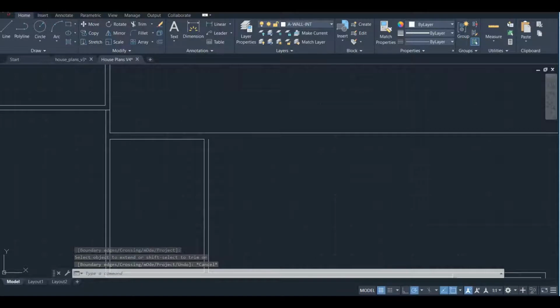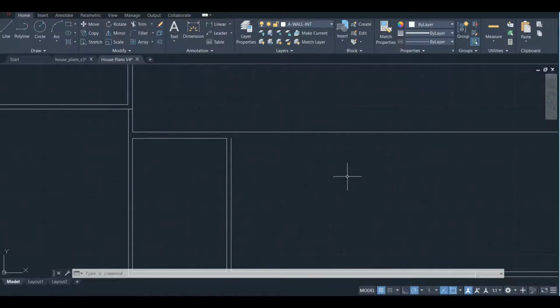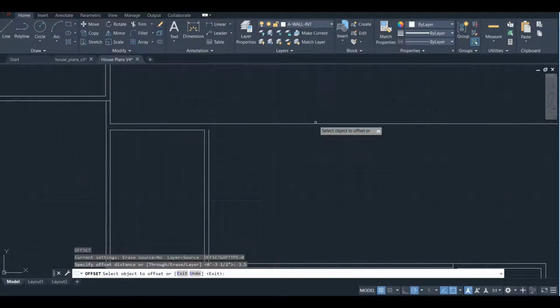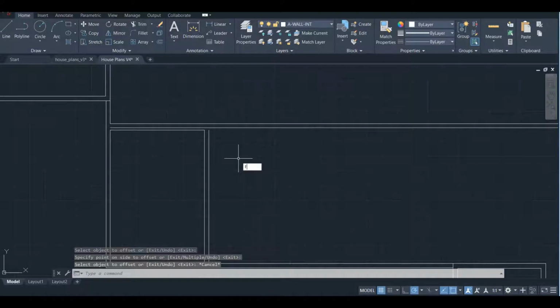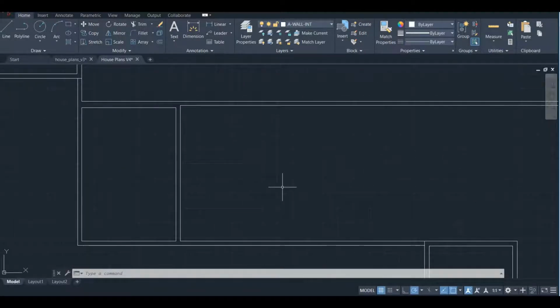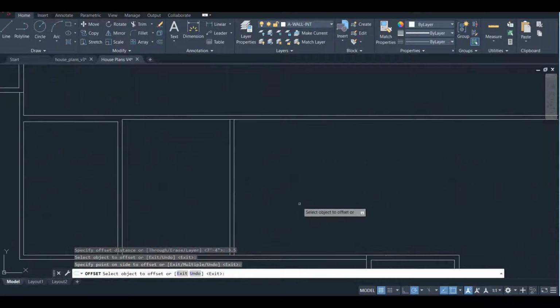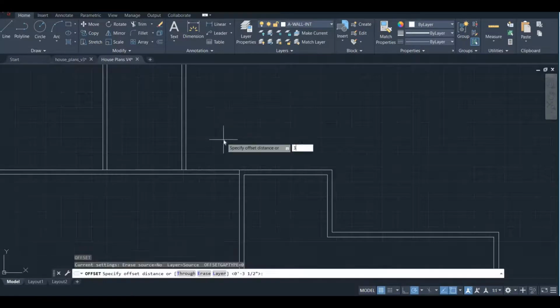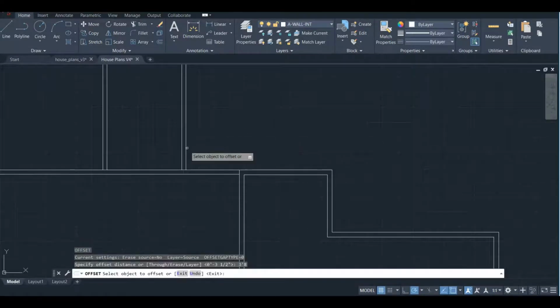For the rest of the wall, though, it is a 2x4 wall. So I again have to offset 3.5 inches, and I can just go ahead and do that, and then I'll use the fillet command, and all of a sudden you can't even get through that little bit there. So this next room is 7 foot 4 inches away. And that should line up with.